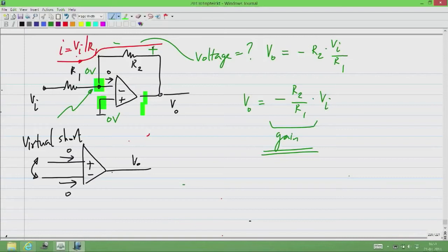So there is a question, is there any chance to change the gain of the op-amp by putting a resistor at the non-inverting terminal? Okay. Now we will see the condition under which the op-amp inputs will behave like a virtual short. And also, just to be precise, it's not the gain of the op-amp that is changing. The gain of the op-amp is A0, which is assumed to be tending to infinity. It is the gain of the circuit which is built using the op-amp. So the gain of the op-amp is A0 and that is fixed.